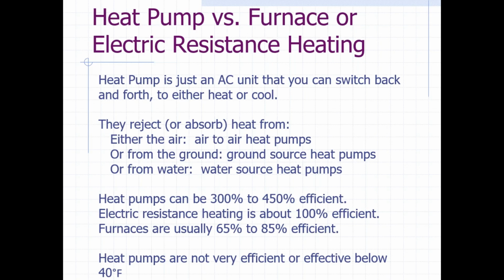What's cool about the refrigeration cycle is, if you're talking about heating, we could do the electric resistance, we get 100% efficient. You'd think, gosh, you can never get better than 100%. Well, that's actually not true. That's what's so cool about a heat pump, because it uses that energy and it moves heat from cold places to hot places. The efficiency isn't 100%, it can get up to 450%. But the efficiency is often like 300%. In other words, for every watt of energy you spend, you're moving 3 watts of energy. So that's really neat. So heat pumps are fantastic, except in cold climates.